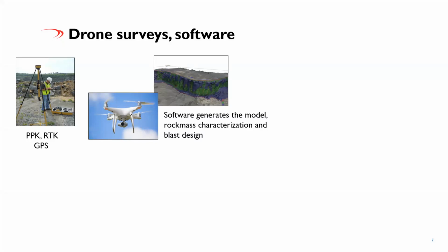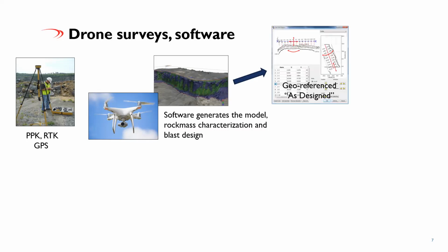And along with that, and most importantly as well, we can then georeference that to whatever coordinate system. It could be a local coordinate system. It could be state plane or some sort of area type coordinate system. Again, that's the key, because with our GPS, we can be assured that we can maintain that accuracy to be able to generate that and then get that model scaled accordingly.